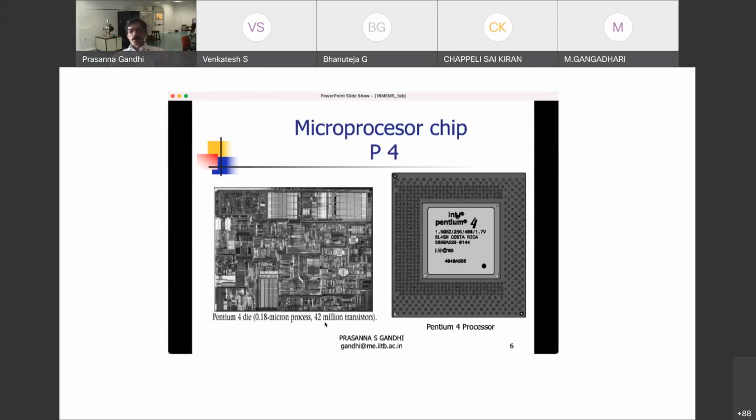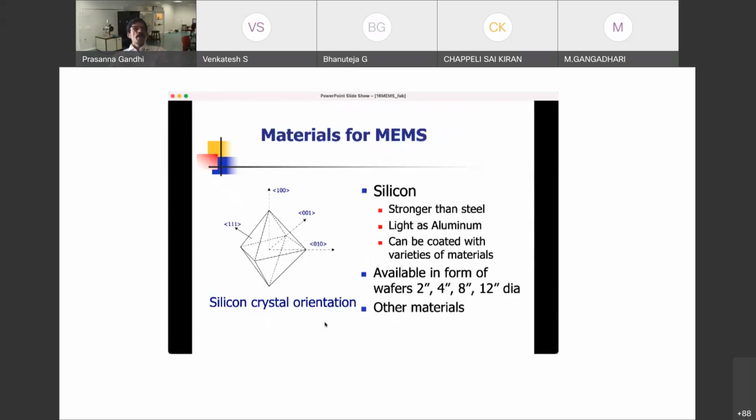We'll see some of these technologies, which are VLSI fabrication technologies, which can be used for MEMS fabrication in some way. Okay, so for the fabrication, we need to know what the material for MEMS is. Typically silicon is the chip material used for fabricating electronic chips or these transistors because it's a semiconductor and it can be doped to give you different levels of conductivity.